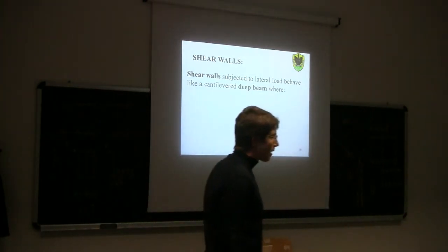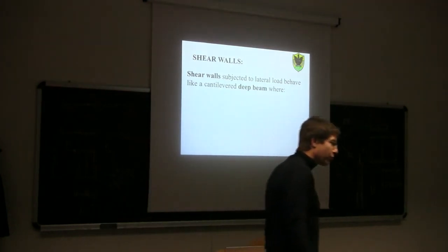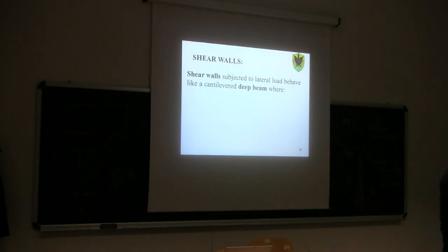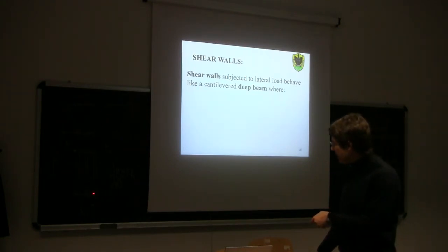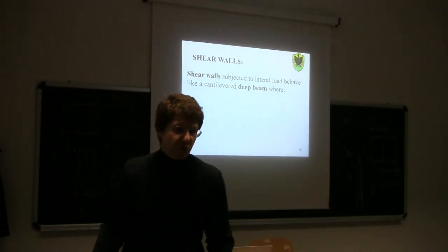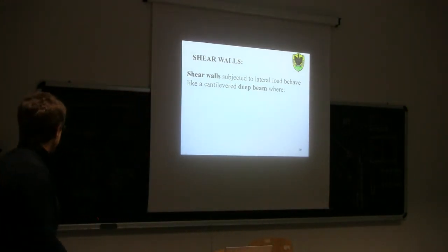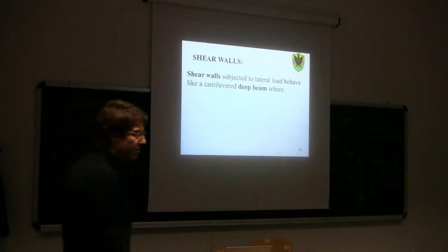But now, if you want a less rigorous, less mathematical approach, say, okay, look, in a cross section like this, how can I calculate in a simplified way the stresses that I have here and here? Without using the Navier formula, which means without having to calculate the second moment of area of this cross section, which is a bit complex.